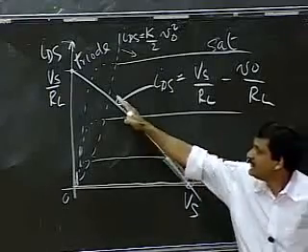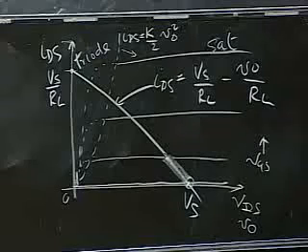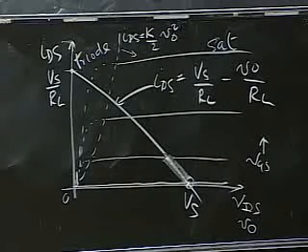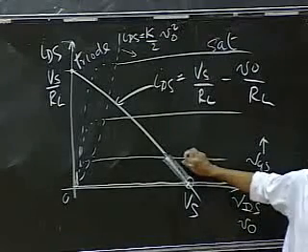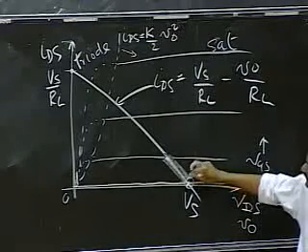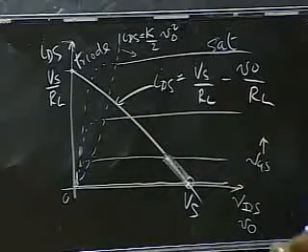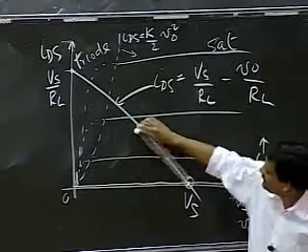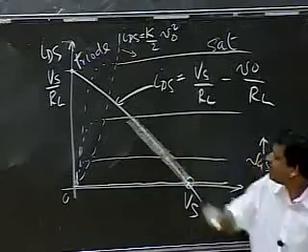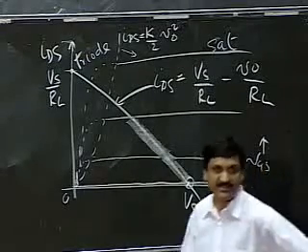Remember, the load line is a constraint that must be met by the output V naught. Okay, it's the constraint imposed by KVL on the output. So the output is constrained to operate in this regime for various values of VGS. As the output keeps going from here all the way here, at some point I exit my saturation region.